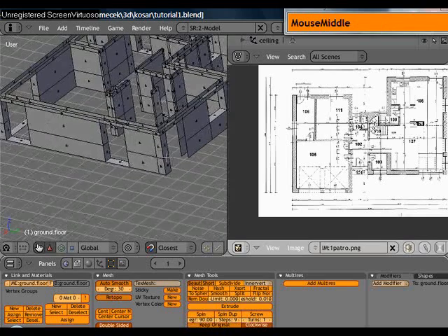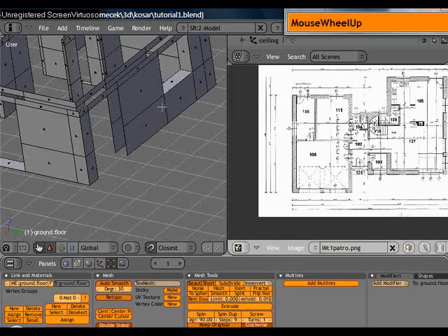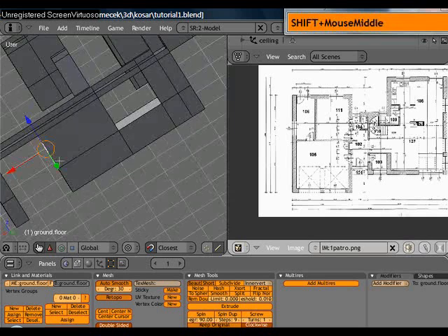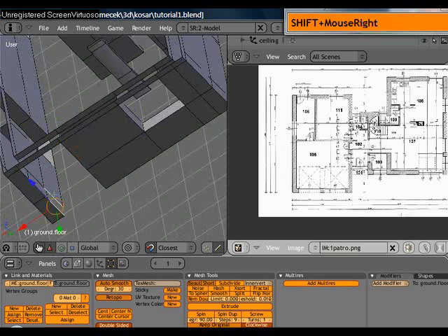And as you see, what happened was in here I do not have this wall in the middle, so this wall doesn't have a side. You can see inside. In here it nicely created faces, but in here I don't have them, so I would have to go to Control Tab to Edge Select Mode, select those edges, F, create faces, and I would do the same over here.